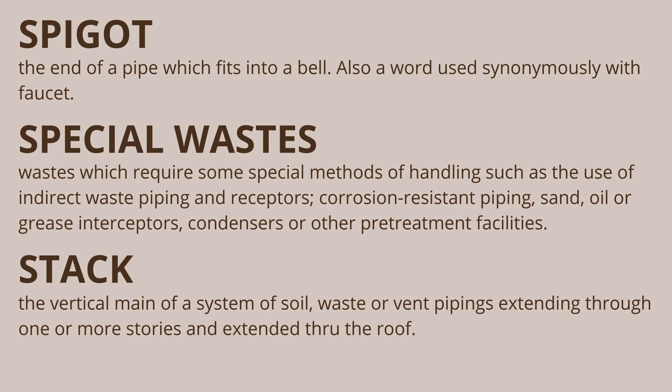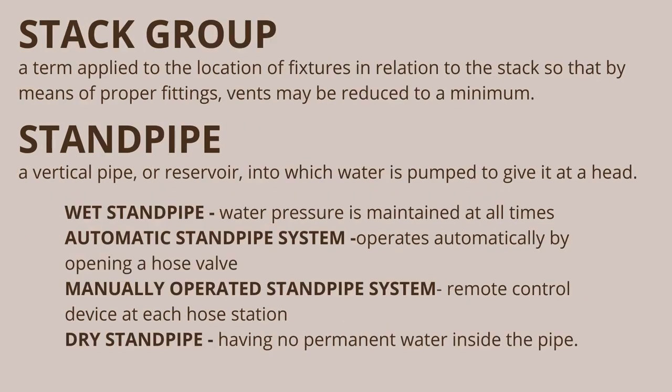Stack: the vertical main of a system of soil, waste or vent piping extending through one or more stories and extended through the roof. Stack group: a term applied to the location of fixtures in relation to the stack so that by means of proper fittings, vents may be reduced to a minimum.